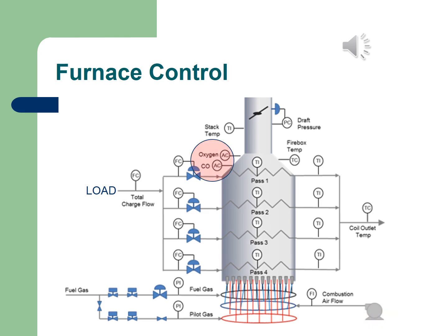One last important aspect here is that there's also oxygen content measurement, so it's an analytical analyzer, and also one for the carbon content. You can actually measure that, and this is important so that we can see, if you can recall from those equations, how much oxygen is still, for instance, in the flue gases, and also how much carbon is still in the flue gases. That will indicate to you if proper burning is achieved. So for that we can use analytical analyzers.